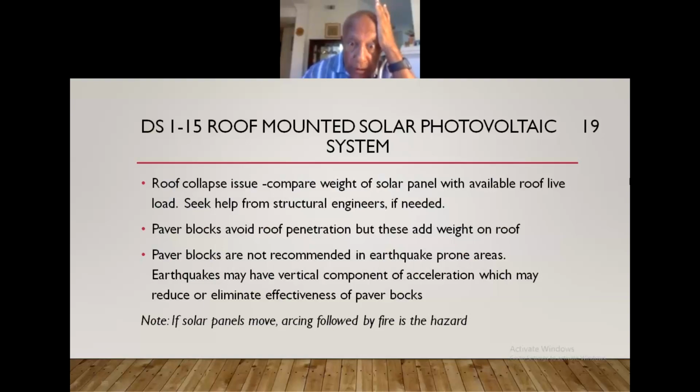So with roof-mounted solar panel systems, collapse is an issue. We need to compare the weight of the solar panels with the available roof live load. You may need to seek help from a structural engineer or find the structural drawings of the facility to figure out what the roof live load is. Paver blocks avoid roof penetration, but they add a tremendous amount of weight on the roof.